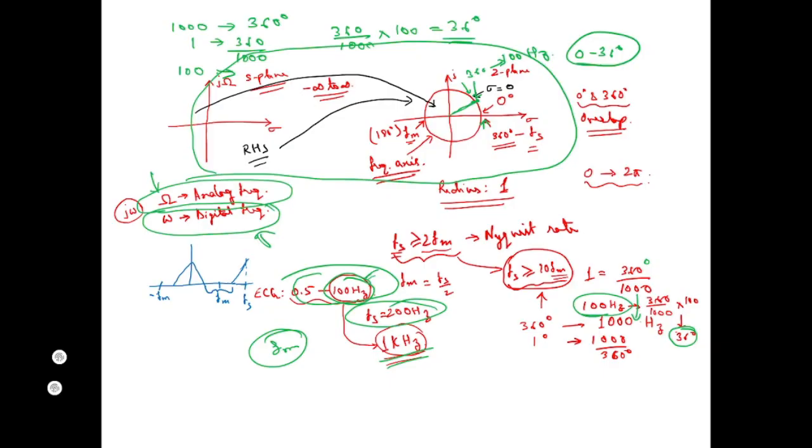There is a sweet point for how you can design your digital filter. A low cost data acquisition system will definitely help you in acquiring the data, but it will restrict your space in the Z plane to design your digital filter. Are you getting my point? Because you will have a very congested area to place the poles and the zeros.